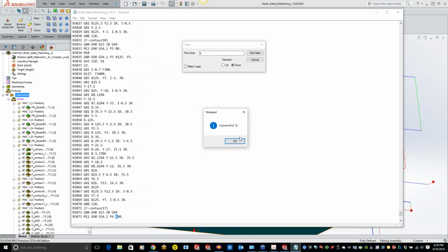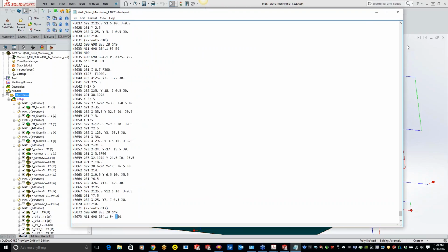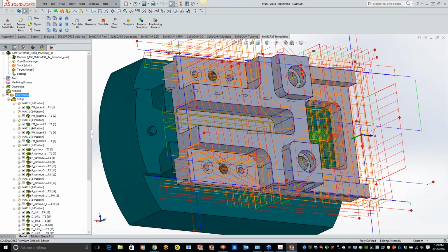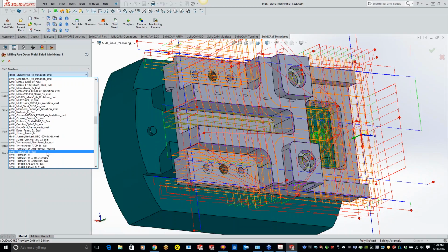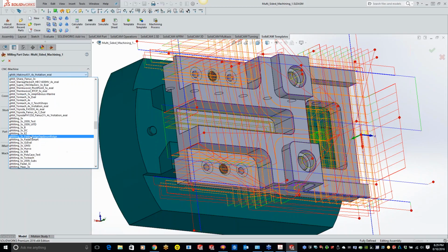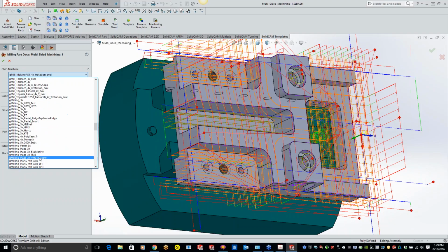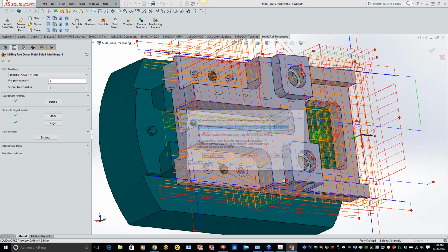Yeah, and Kevin, that's actually a really good point, because some of those older machines have memory limitations. So just taking out the repeated B-axis rotations or line numbers or anything like that, obviously that's perfectly customizable. So yeah, that's a really good point.